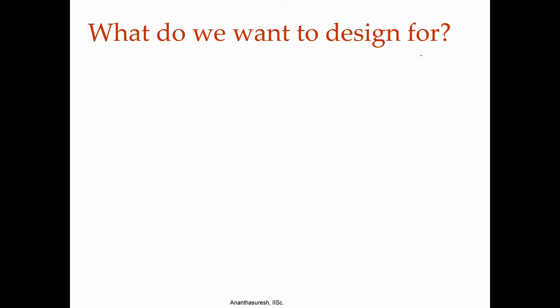So, here in the context of compliant mechanisms, what do we design for? What do you want to design for? If you recall, so far our interest has been function generation. That is, if I have one point and another point, I say my input is in that direction. If I apply input in that direction, I want, let us say, output in that direction. That is the kind of problems we have solved with rigid body modeling based design method, as well as structural optimization based design method, especially the topology optimization method.